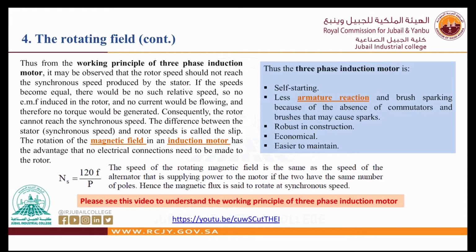Now the rotating field, the working principle of the three-phase induction motor: it may be observed that the rotor speed should not reach the synchronous speed produced by the stator, right? If the two speeds become equal, we have a stator speed, right? We have a rotor speed. If we have the same speed here, there would be no relative speed. We will have zero speed.